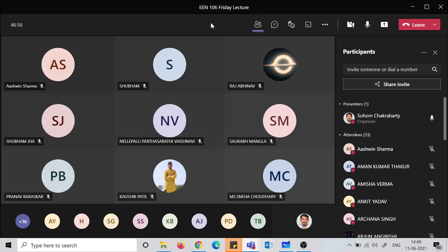Are there any doubts, any questions? So please understand the difference between the D-MOSFET and E-MOSFET. The difference is in the construction, and that leads to the functional difference. D-MOSFET has two modes of operation. E-MOSFET has only one mode of operation. And how the modes are established due to the Vgs value, that you need to understand.